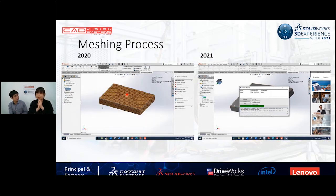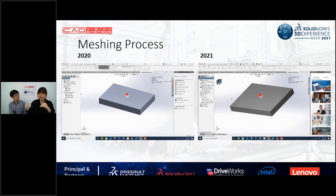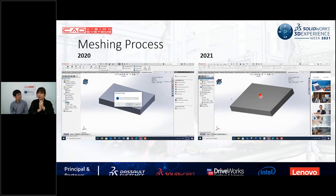Previously, after we had applied the boundary conditions, everything was referring to the mesh conditions. But in this new release, the things that you set up are only referring to the geometry itself, so the meshing might take some time to resolve to get an accurate result, because everything will be analyzed based on your meshing. But the boundary conditions you set will only refer to the geometry. So unless you make changes to your geometry, you don't need to do anything to update the mesh.